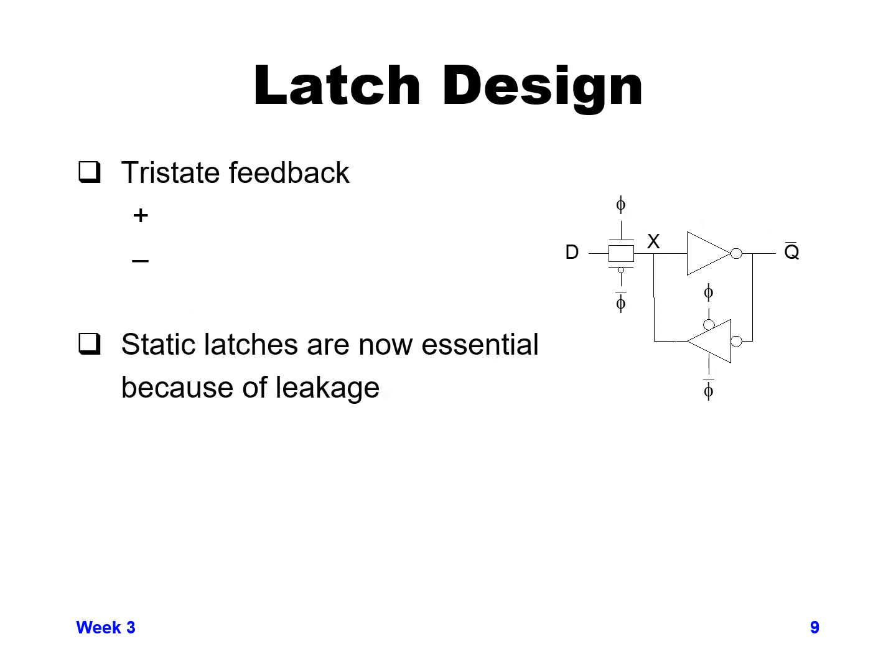Adding yet more to this latch design that we've been working up, instead of just having an output inverter, we can add a feedback element to the internal X node. This has the benefit that it's now a static value.